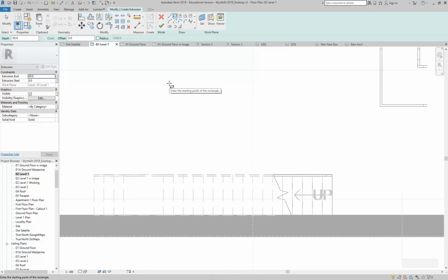So you know your standard board thicknesses? Yeah. If you're making a cabinet, it's generally made out of standard board sizes, which start at about 16mm and go up to about 35 or even thicker, but it's about that range. So you can even round it off and say 20mm for your boards and just make them all that thickness.